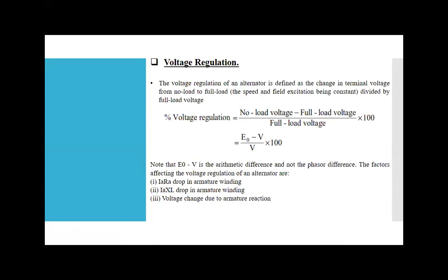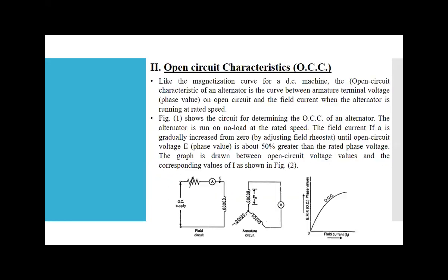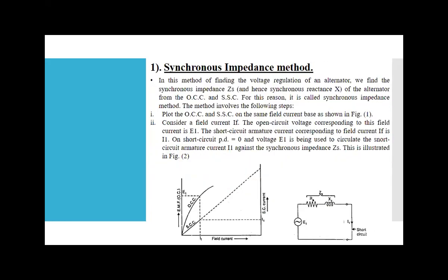I think you already learned these methods in your laboratory sessions, because most of the time you perform the experiments on the synchronous impedance and the ampere turn or MMF methods. So in the last lecture, we learned about the synchronous impedance method. It is the easiest method to find the voltage regulation.